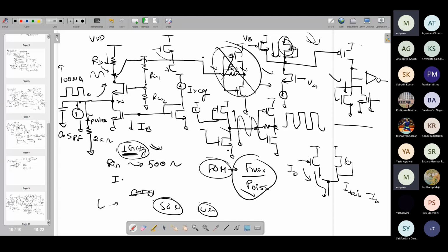So here the challenge is bandwidth is also large, and you also need the input impedance. Here, at least before the amplifier, if not 500, you need at least 100 millivolts so that this inverter can work properly. So if I assume 100 millivolt at least, then 10 to the power of 3 gain is not that challenging if you get say 30 gain in 2 stages. It may be possible. For 30-30, you will have to aggressively skew the W by L sizes, and you may have to use more than 2 stages. Here I'm giving only 2 stages. You may have to use more than that.